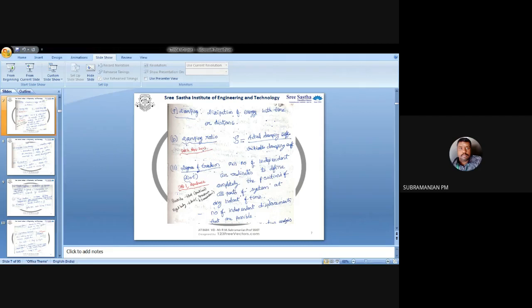So we discussed what resonance is. When the natural frequency coincides with the frequency of external excitation, resonance will come. And you can see in the sketch a single degree of freedom, that is a spring mass system. You have 1 degree of freedom, that is, the mass is allowed to move in the x direction alone. For 2 degrees of freedom, you have two masses, so you have x1 and x2. And for 3 degrees, you can see 3 masses and 3 displacements.